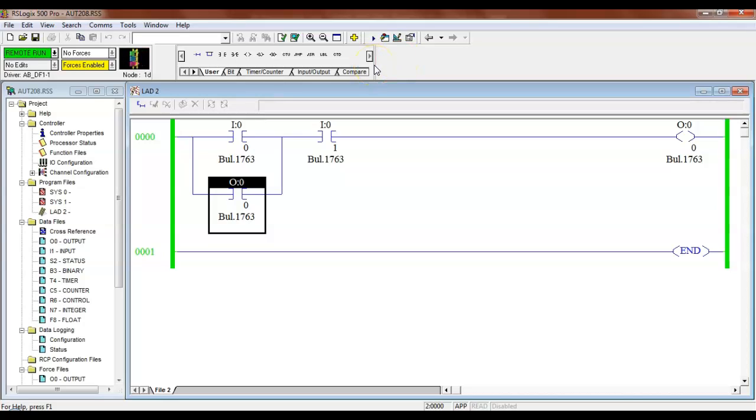So I'm going to come over here and I'm going to energize 0. And without even a meter, I know that this input is being delivered to my PLC because I'm hitting one of my switches. So normally in relay logic, what we'd have to do is go out there and get a meter and see if we got power or measure the voltage across the switch or vice versa. Here, the PLC application tells us exactly if the PLC is seeing this information.